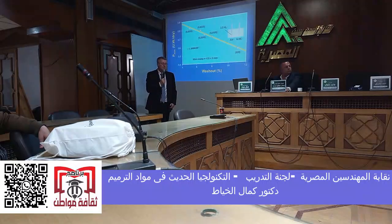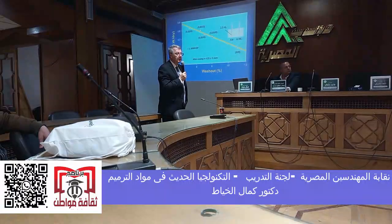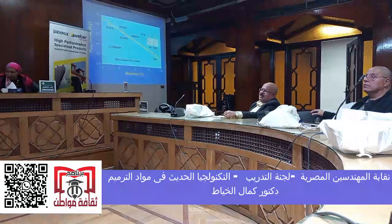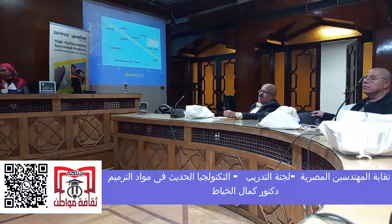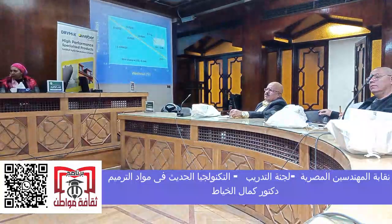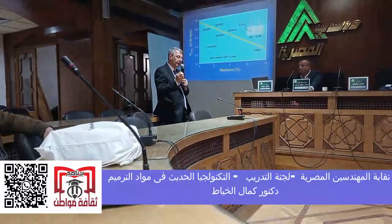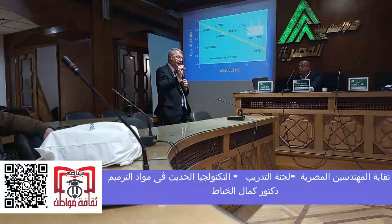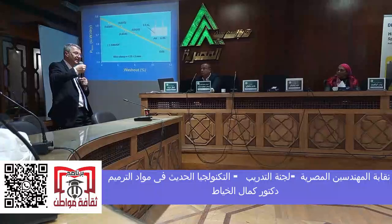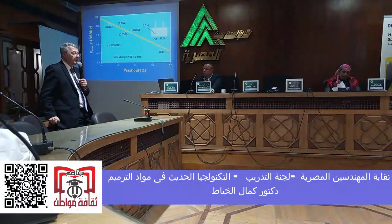But why did you do a pull-out test? What is the benefit of a pull-out test in this case? So this was another project. We were doing underwater repair grouting for underwater repair anchors, but I'm showing you the behavior of the material. Pull-out is a very good characterization of the bond between the steel and the grout. If the quality of the grout is low, you're going to feel it, not in compressive strength, but in pull-out. So it's an indication. Next.